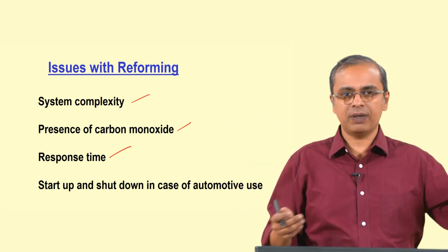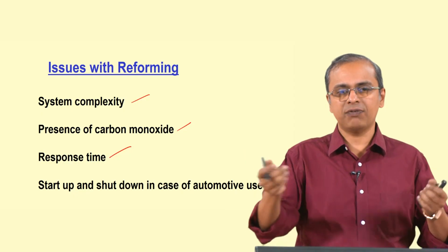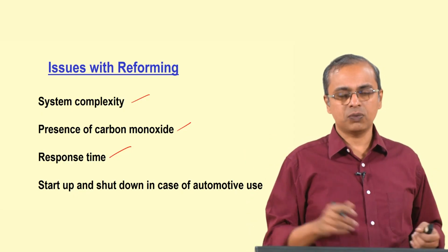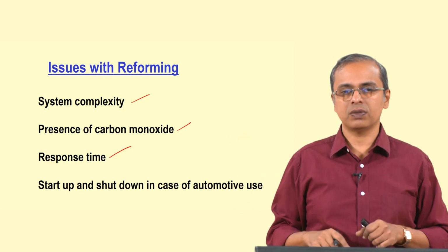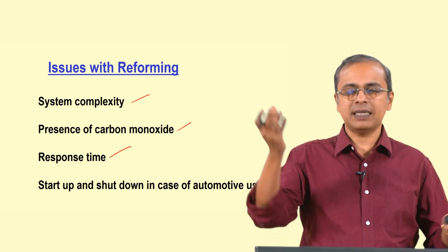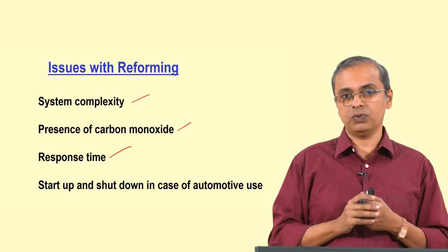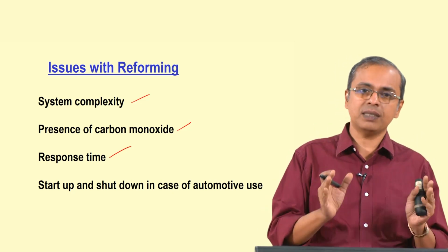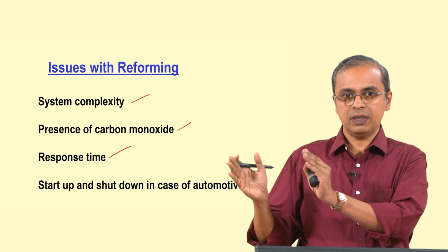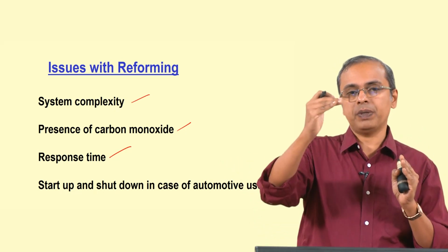You walk in and you just start flipping on the switches at different places, you switch on the TV, you quickly walk into the kitchen, you turn something on, you turn on your washing machine. In a couple of minutes suddenly you have changed the complete power demand on the power source in your house. Now, if a fuel cell system is the only thing that is powering your house, the fuel cell system should suddenly ramp up in power.